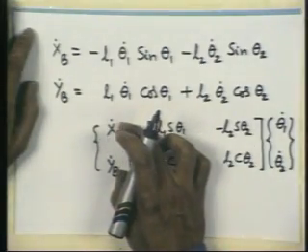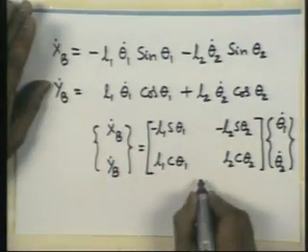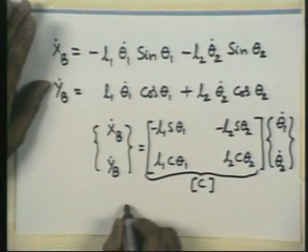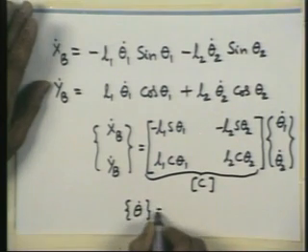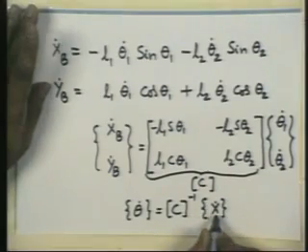Given x b dot and y b dot, that is the end effector's velocity through a particular position. So, once you have specified a position, I am assuming that you have already solved the position problem for the joint space velocity positions. So, therefore, theta 1 and theta 2 are again known to you. So, given x b dot y b dot to be achieved at a particular position, determination of theta 1 dot theta 2 dot also is reasonably straightforward. You invert this matrix. So, if I call this as some C, theta dots in general is C inverse x dot,